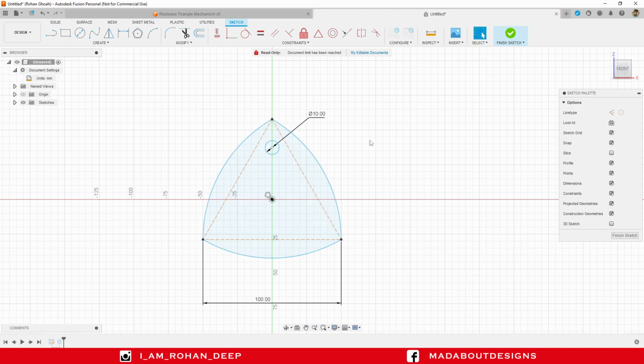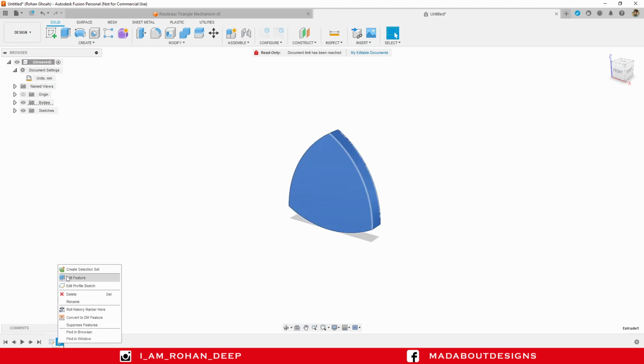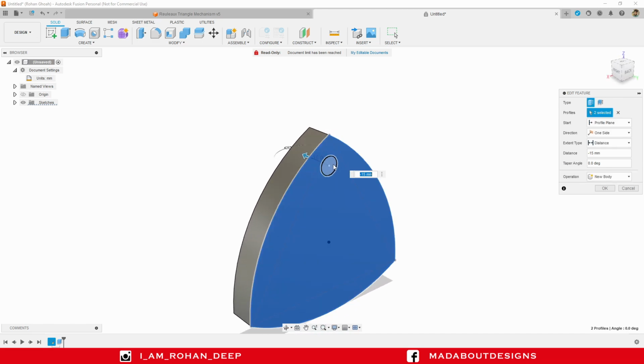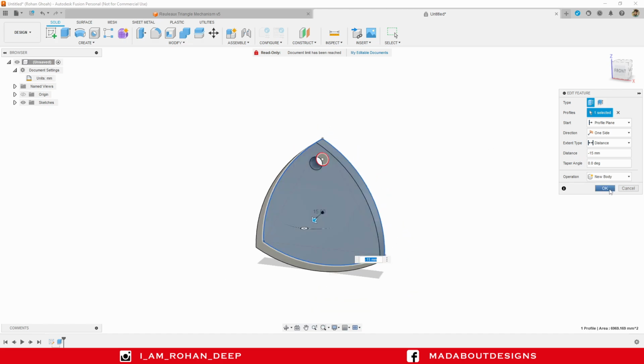Press D to go to Sketch Dimension. Select the center and the center of the circle. Provide a vertical distance of 42 mm in between them. Finish sketch. Edit the extrude. Deselect this circular profile. So a hole has been created on the triangle. Click OK.